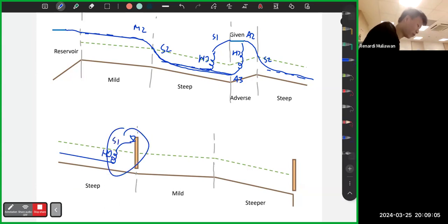Okay, and actually for the sluice gate case, it's always hydraulic jump S1. Either that or M3 hydraulic jump. Yeah, it's always that kind of pattern. Okay, then mild slope, right? So M3 hydraulic jump, because we start down below. Mild slope, yn is here. So you need something, right? So it's an M3 hydraulic jump.